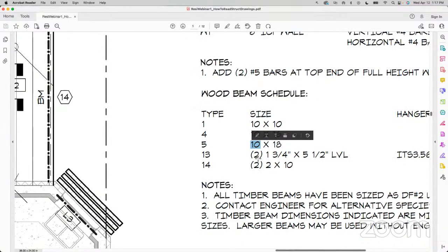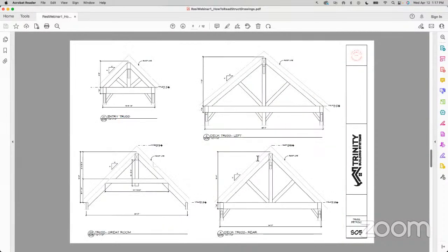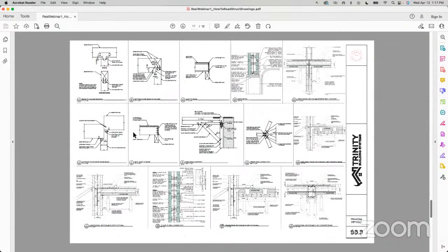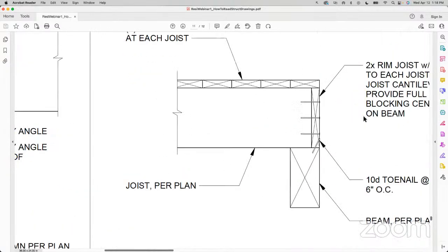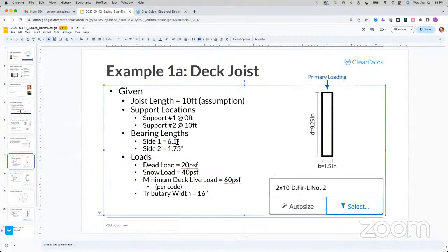So if we come back here, and per our engineer's comments here in the chat, thanks a ton, we actually don't have 2 times the rim joist. There's actually only 1, so it should be 1.5. We've got this 10 by 18 minus 1.5. So 9.5 minus 1.5 will give us 8 inches. Let's pop back out here. We'll change this to 8.